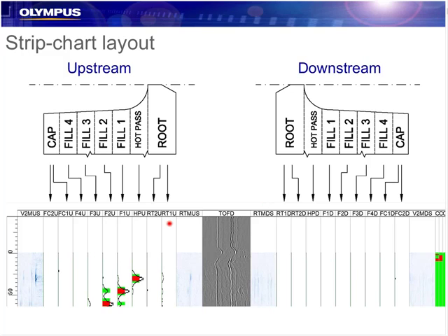You know, typically these zones are focusing mainly on the bevels for lack of fusion. We want to make sure we don't miss any internal defects as well. And then we also have coupling channels. We want to make sure that the probes are adequately coupled all the way through the scan. There's no coupling problems affecting transmission of sound and therefore detection of defects. So we'll look at this a little bit bigger, but just kind of trying to lay out the general process at this point.